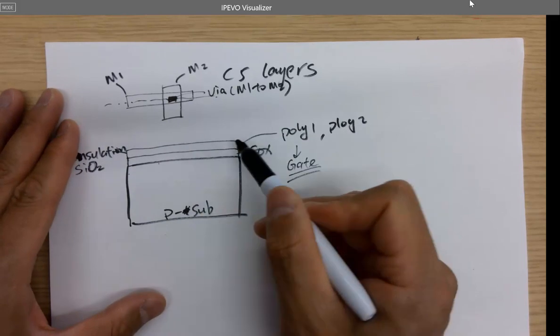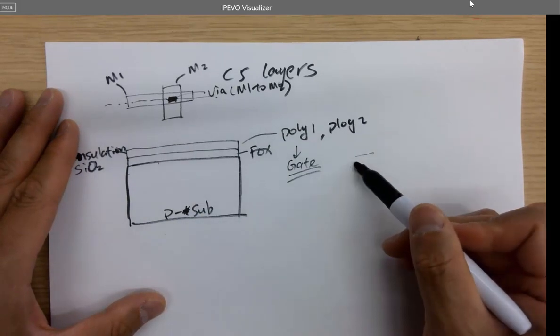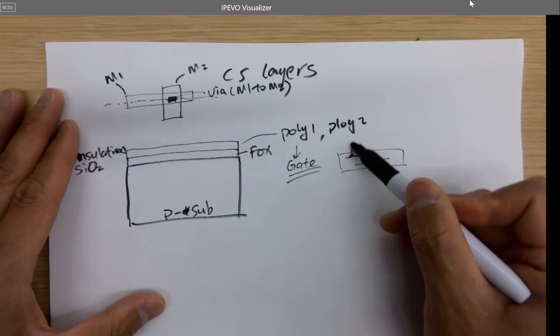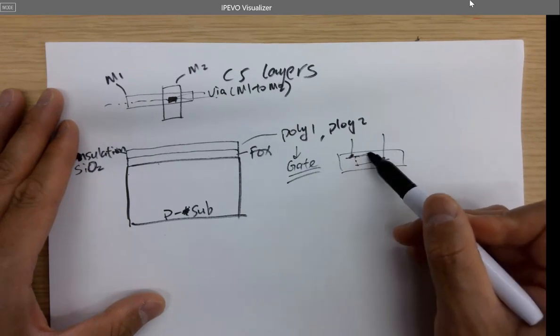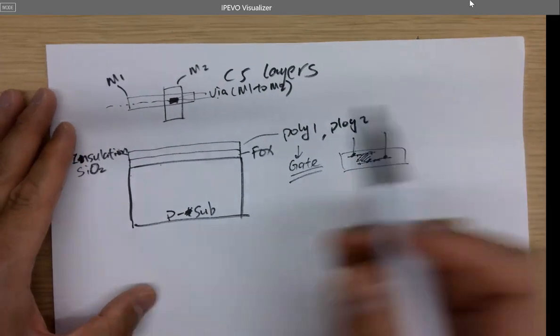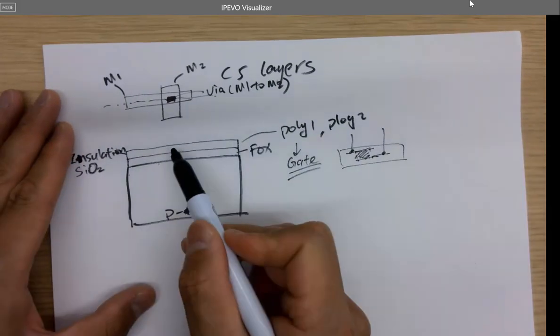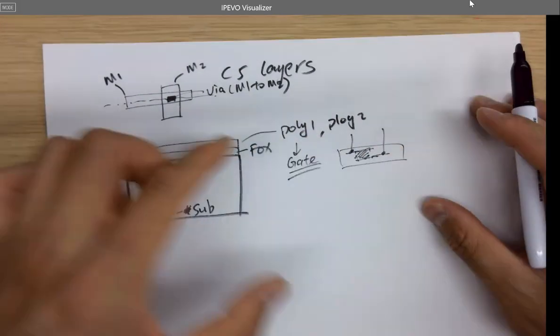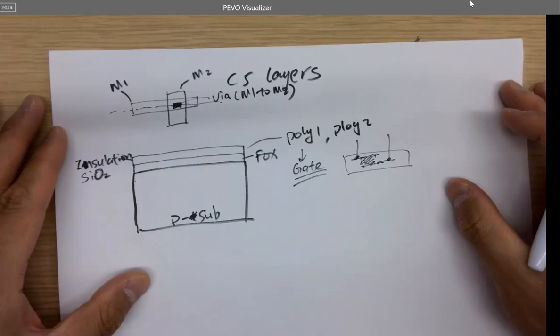So you have poly 1 and poly 2 in the same insulation layer, and a metal trace. This overlapped area is going to form a cap. They're all in the first insulation layer, but we don't have a gate or any poly layer drawn in the layout, so we don't have to draw anything over there.